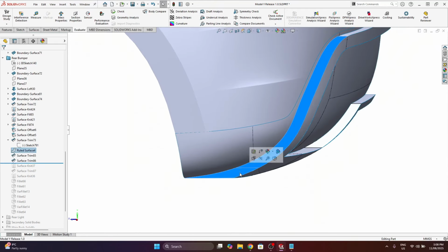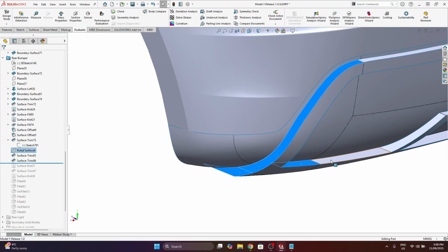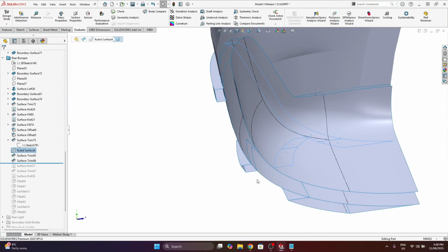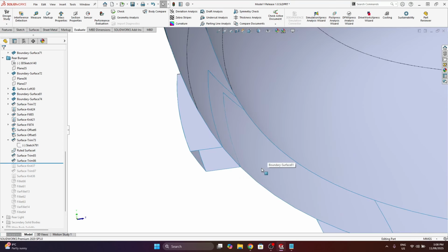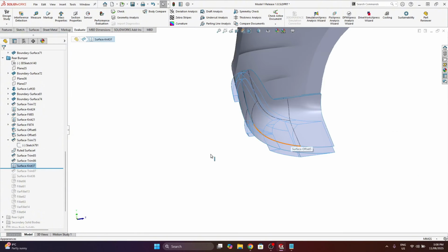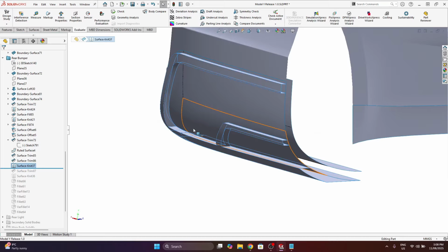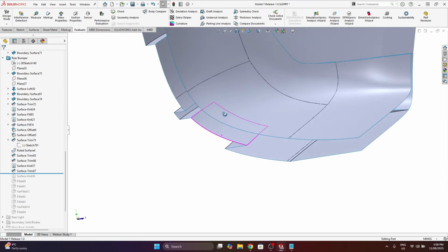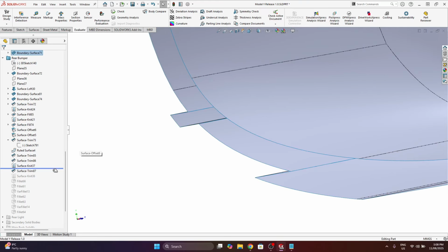So now what I've done is introduce all these surface edges that go straight back, and now line up with this surface body. Knitting them together, here I'm doing a surface trim of these inside sections.